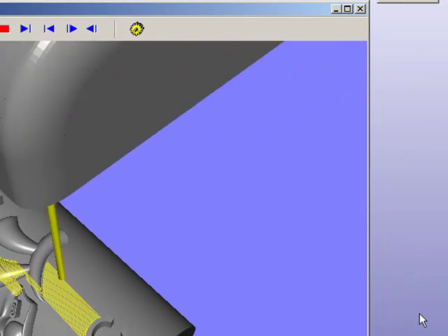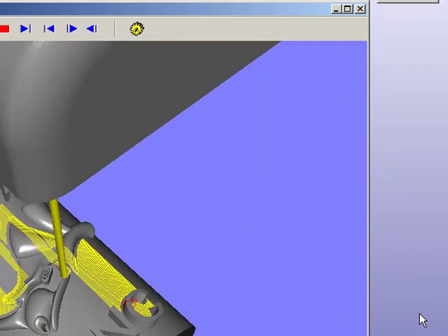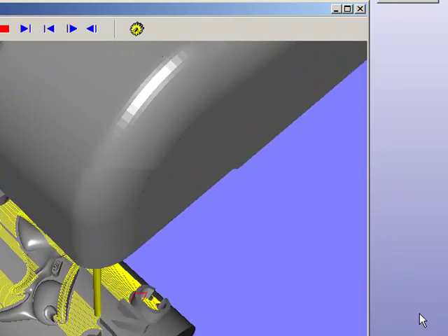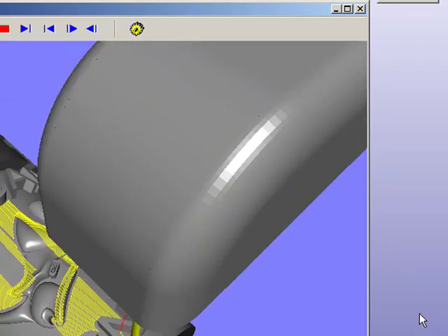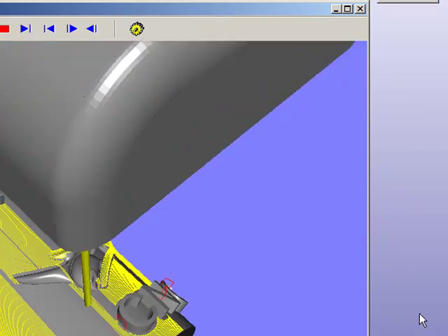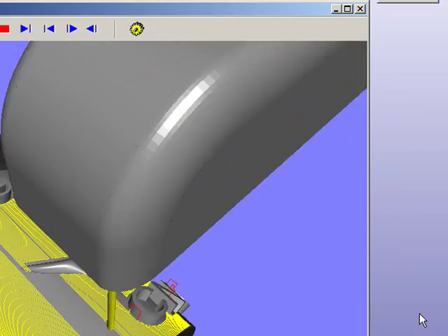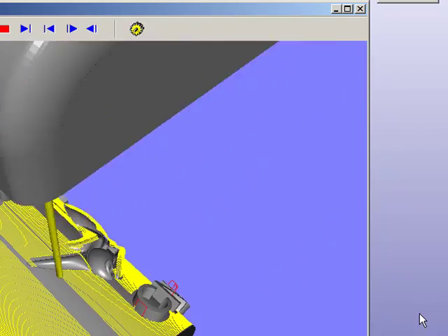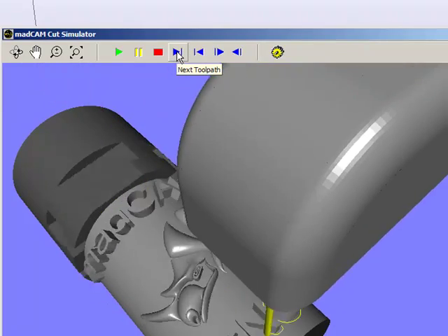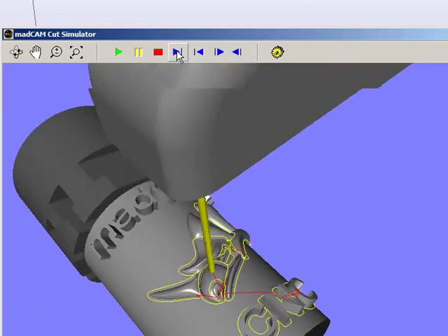And madCAM is creating the planar finishing on the relatively flat surfaces, even if using the simultaneous 4-axis. So the toolpath will never go down on steep sides, because the steep surfaces are already machined by the Z-level finishing. And there we have the pencil tracing toolpath.